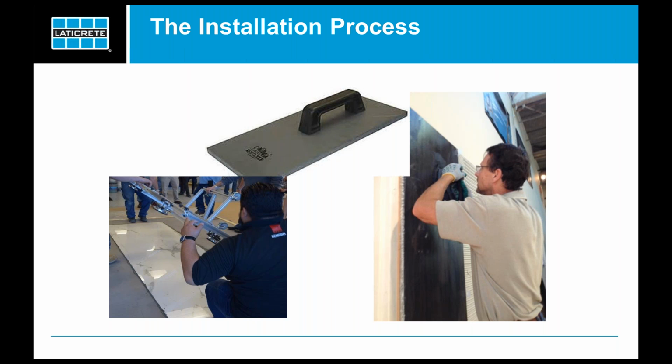So this is where it's a little different as well. In many instances, typically you would use a rubber mallet or a beating block or something else to embed the tile, or maybe you push it back and forth, you slide it back and forth to gain your type of coverage. With these materials, it can be challenging to do that.